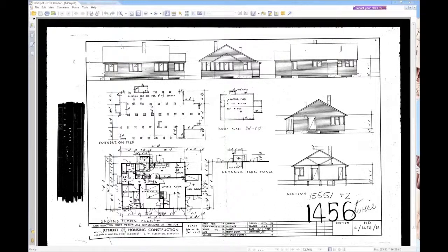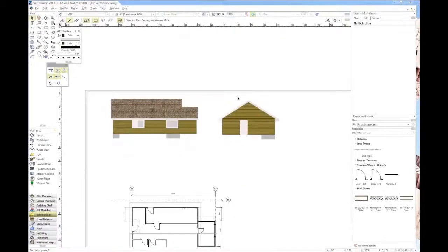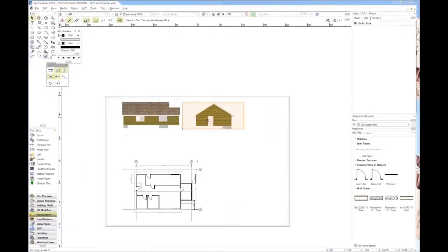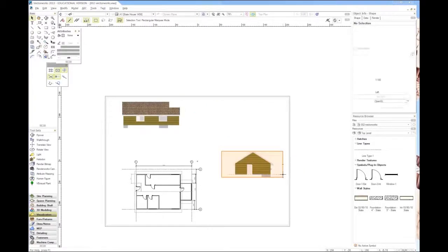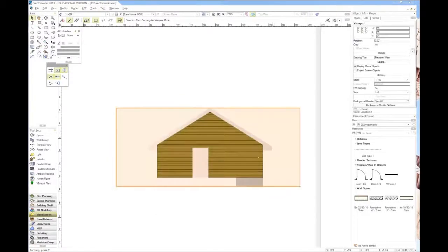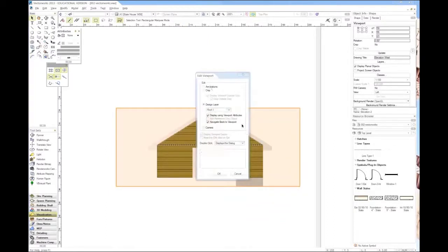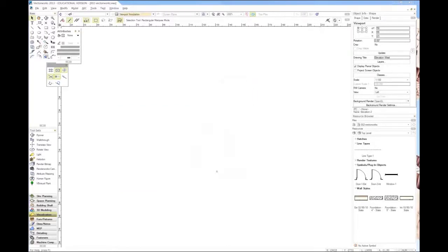And then the next thing you need to do is figure out how you add these dimensions. So, was it 2.5? Oh, 2 feet 2 inches. So that's this one over here, right? So I'll put that down there. And then to add dimensions for that drawing, what we want to do is double click on it and go edit annotations. And then, yep, we'll level that.